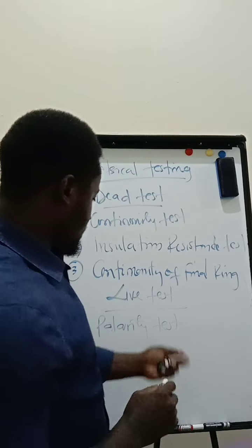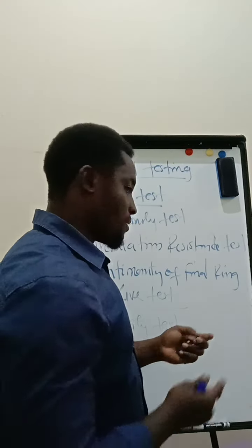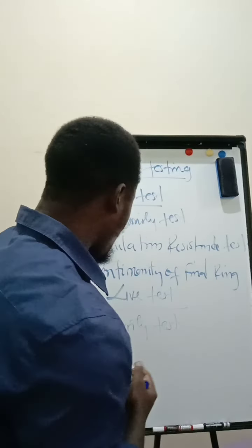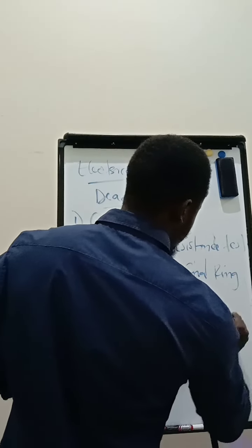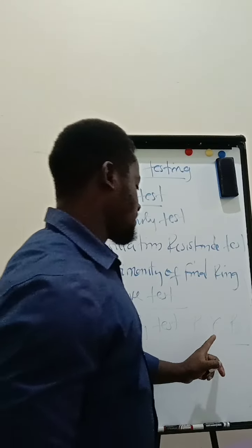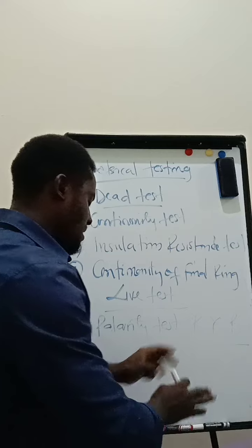So the polarity test is to ensure that all the different wires which we've connected or placed in our panel board are connected properly. I'll give an example of R, Y, B phases. So we have the red wire, the yellow wire, and the blue conductors all connected accordingly.